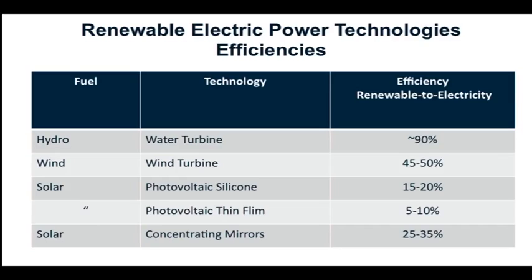That's not limited by the Carnot efficiency, we call it, or the heat equation for the second law. But the Betz limit, no matter what you do, if you get rid of friction and do everything in an ideal manner, is 58%. So you can't extract more than 58% of the kinetic energy in the wind and convert it to shaft power. It's just the limits of the laws of nature.